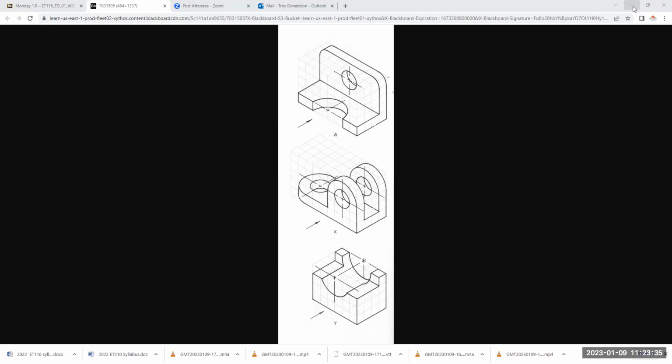Yeah, so I got to round it. I don't use arcs. I don't like them. I just use circles and trim them up because trim's really been improved quite a bit. So I think, what was that? 2, 4, 6, that was 8 across. So then what I would do is just put in a construction line, which is going to be down 4, and then go with the circle there to there.